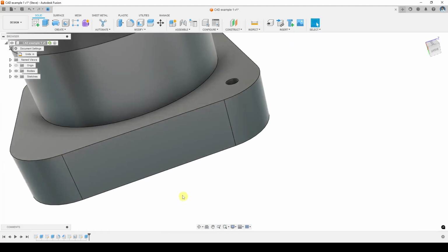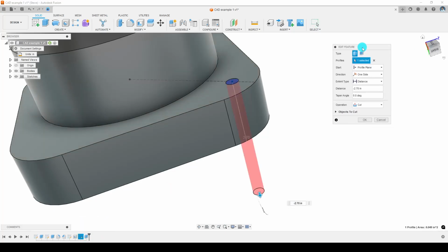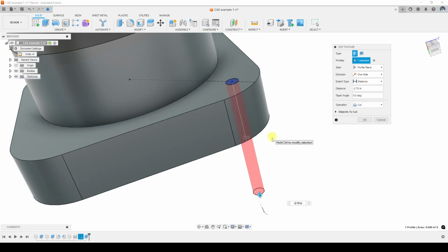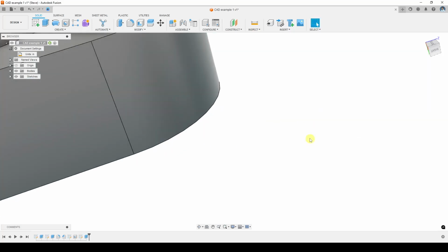And when you extrude a geometry into another geometry that already exists, it'll be a cut. So I'm going to look down here at that extrusion I just did just to look at those details. I'm going to double click. It's in the design history on the bottom. I'm going to double click it, and I can see that under operation here, I can actually make it a new body and make it a solid body. I can have it join the other geometry that's there, or I can have it cut. Okay. So it's cutting, click OK.